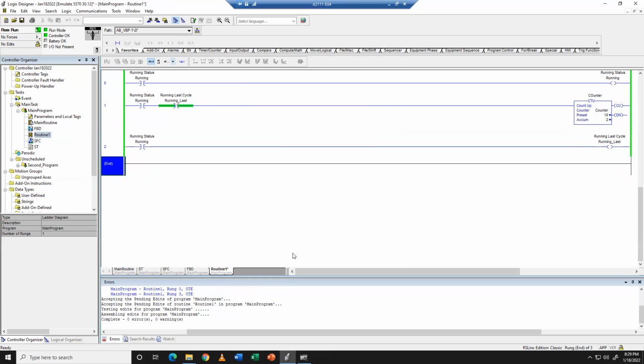I can't tell you how many problems I've come across where the order of operations was programmed in such a way that it could only work if 1, then 2, then 3, then 4. So if you've got a sequence, like we were getting into with sequential batch or sequential flow chart, if you have a process that's very dependent on 1, then 2, then 3, then 4, and you're never going to have something deviate from it, perfect. But if you have a process that might go 1, then 2, then 1, then 2, then 3, then 1, you really need to pay attention to your order of operation.